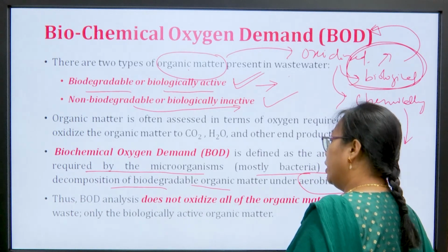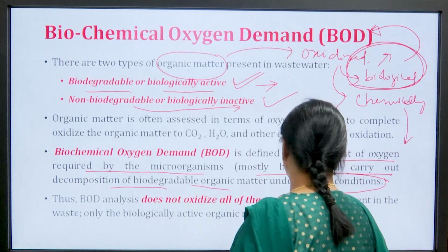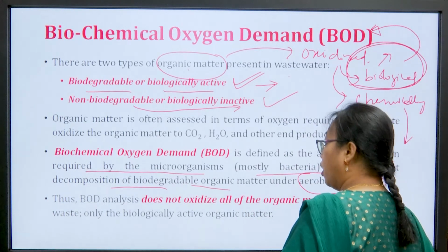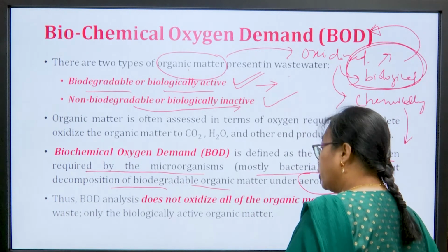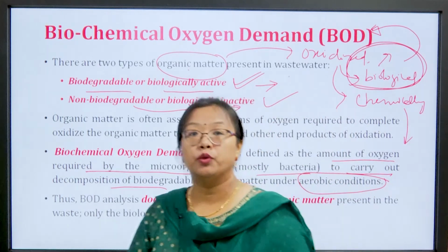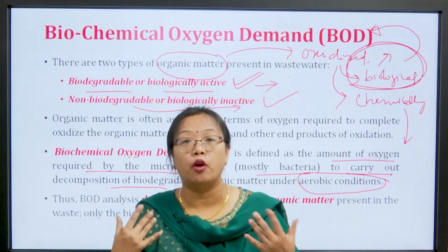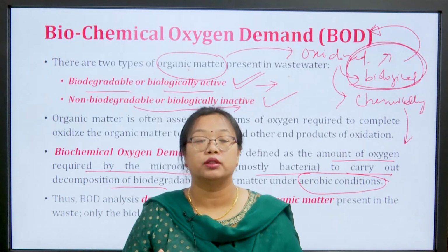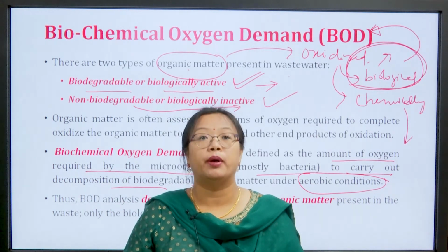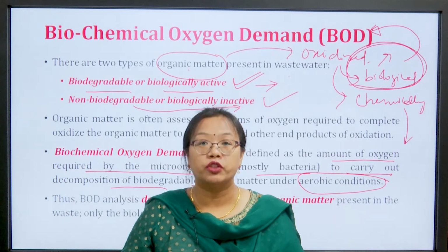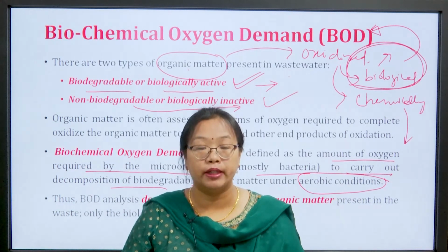Thus, BOD analysis does not oxidize all the organic matter present in the waste, only the biologically active organic matter. So, when we talk about BOD, we are not talking about oxidizing the whole organic matter, we are only talking about oxidizing whichever is biodegradable, which is biologically active, which can be degraded by the bacteria.